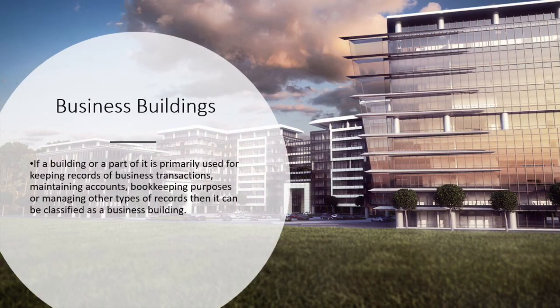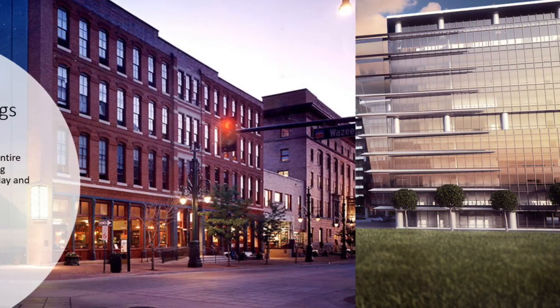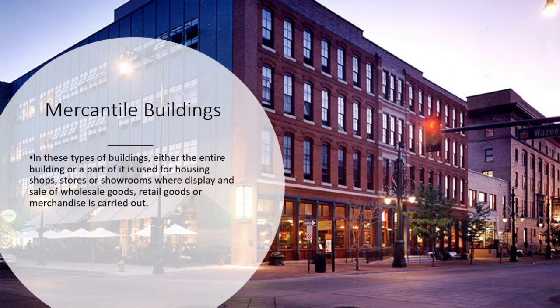Business buildings. If a building or part of it is primarily used for keeping records or business transactions, maintaining accounts, bookkeeping purposes, or managing other types of records, then it can be classified as a business building. Mercantile buildings. In these types of buildings, either the entire building or part of it is used for housing shops, stores, or showrooms where display and sale of wholesale goods, retail goods, or merchandise is carried out.